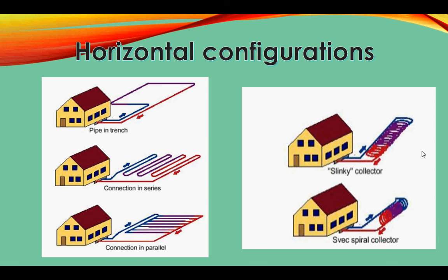There are also several horizontal configurations available. In a series, it is easier to remove trapped air. There's a simplified flow path, and the heat transfer is higher per foot of pipe due to a larger diameter pipe being used. However, it requires more transfer medium, has a larger pressure drop through the piping, and longer trenches are required.